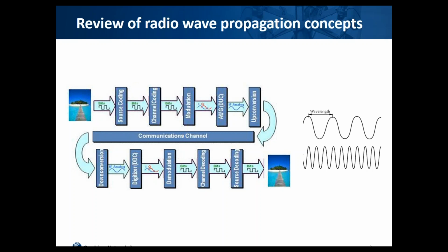Many communication systems automatically adjust the amount of redundancy added by the channel coder based on the varying channel conditions. This means that if the channel degrades, the transmitter can add more redundancy bits and make the signal more robust. But if the channel becomes cleaner, the transmitter can reduce the redundancy and send new data instead.